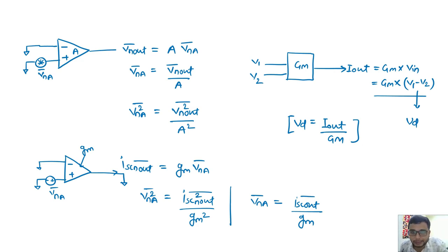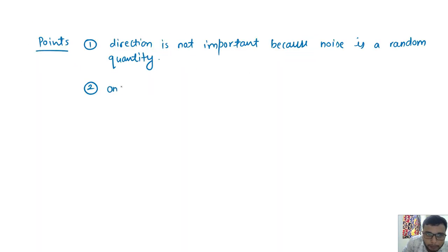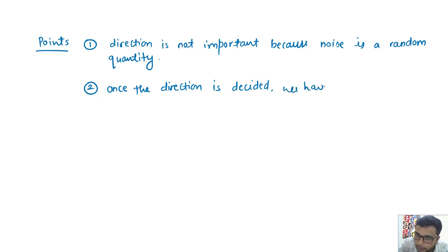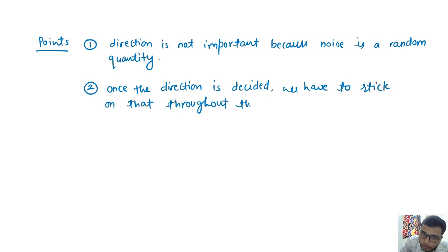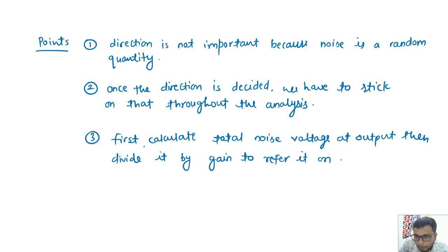But for the noise, the direction does not matter. First thing, for the noise, once the direction is decided, we have to stick to that throughout the analysis, then divide it and refer it to the input.